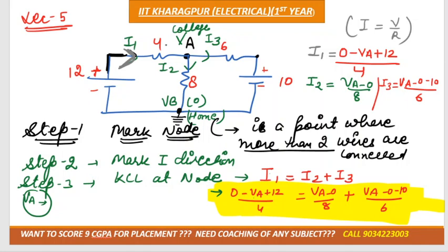Now if you do it by mesh analysis, there are two meshes, two variables, so you have to make and solve two equations. But with nodal analysis there is only one node, the main node. The upper node is known as the main node, and the lower grounded node is known as the reference node. So we'll have one main node, one variable, and one equation. Understood?